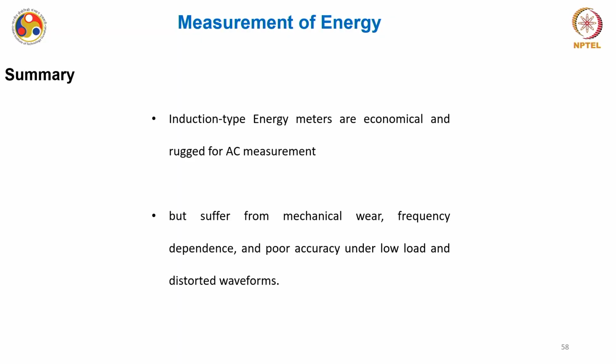If I summarize whatever we have discussed, the induction type energy meters are economical, and they are not only economical, they are also rugged devices. You have electromagnets, an aluminum disc, and the permanent magnet for the braking system. Overall the construction is very simple and cost effective, and that's why they are very popular.